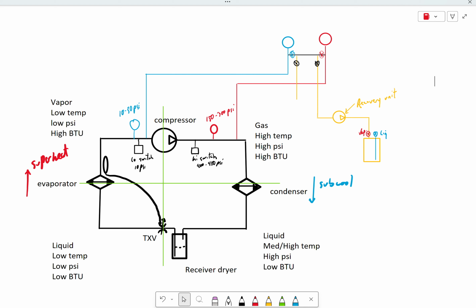So, anyways, you get your system emptied out. You do any repairs that you're supposed to do to the system. The next step that you would have to do, what is it? Vacuum it out. After any repairs, we are obligated to do a leak test. Now, is that going to be a vacuum test? Is it going to be a pressure test? Do we maybe want to do both?